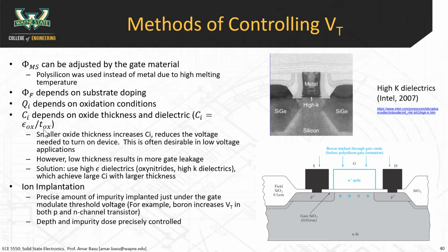The thickness of the dielectric and the dielectric constant of that dielectric material determines the capacitor properties. So epsilon oxide, that's the dielectric constant of the oxide material. That's determined by what material you use. And then Tox is the thickness of that oxide material. All right, notice that the Tox is on the denominator. So what happens if you go to thinner oxides? What happens to the capacitance? It increases. It can increase quite substantially.